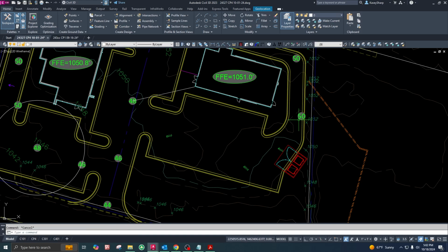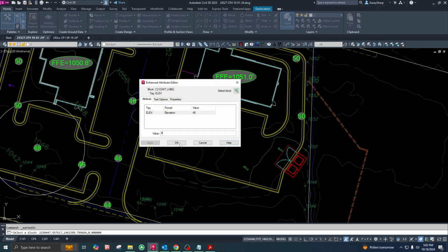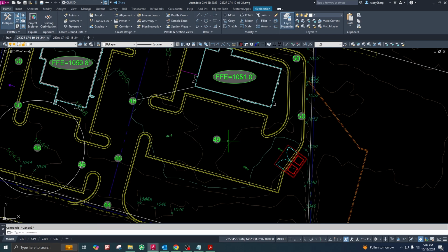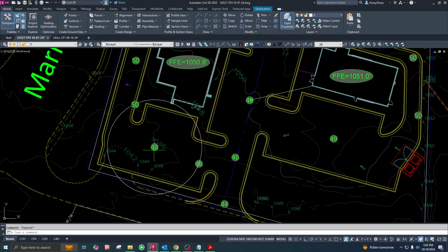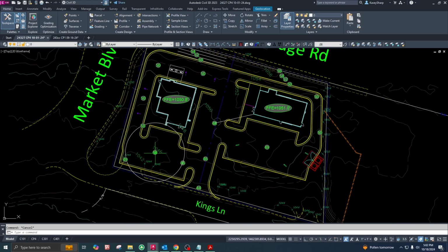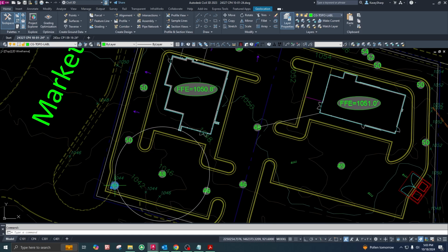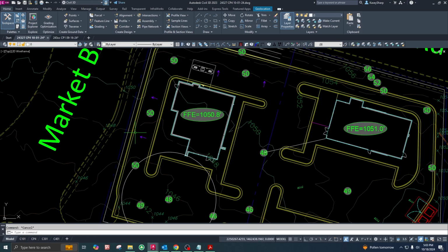Okay, keep drawing our circles to use as a reference. 40. Well, so we can go a little bit farther than that. Drop a 48 right there as a low point. This guy might even be a 49. Okay, so we're going to have inlets right here at a low point, right here at a low point, right here at a low point. So we're going to have 49 up here in the corner.